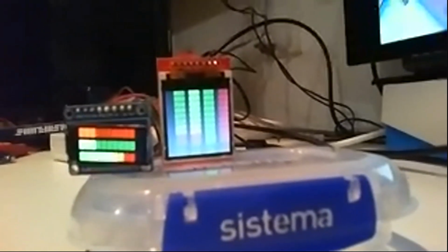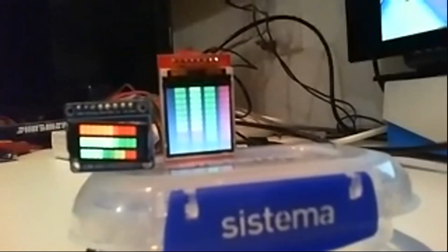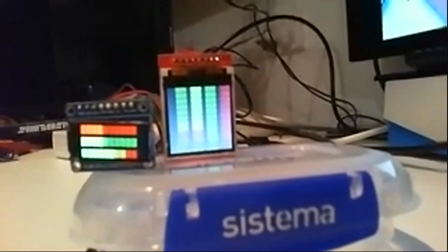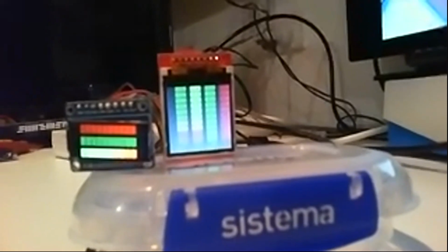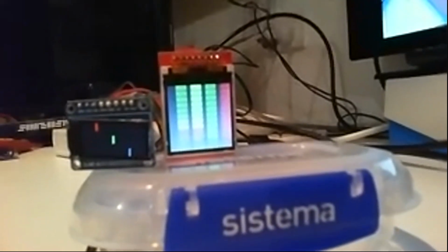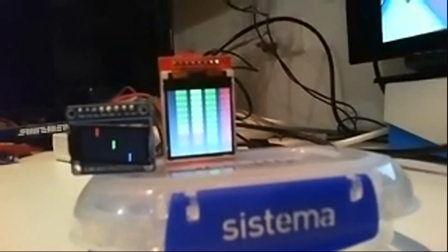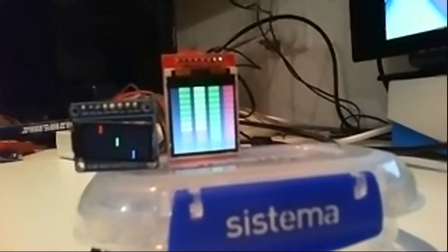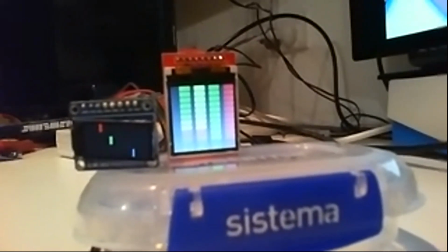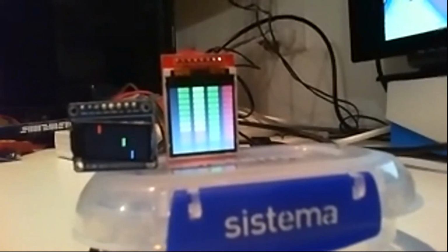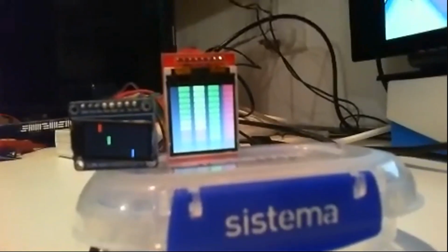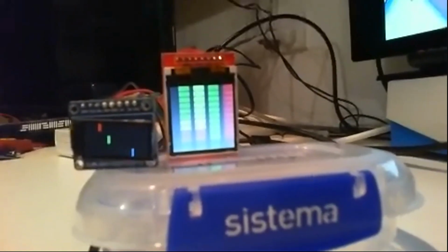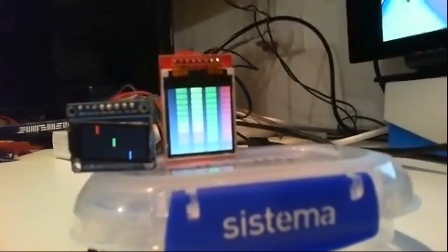So if you want to fill the whole screen, for example, then you just define your top left as 0, 0, tell it how many bits, 128 by 128, and then you can just stream out the bits. But if you want to set individual pixels, you have to define a window that's 1 by 1, and then you send out the pixel data.